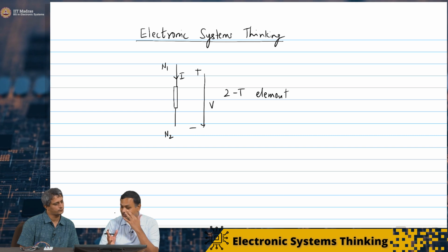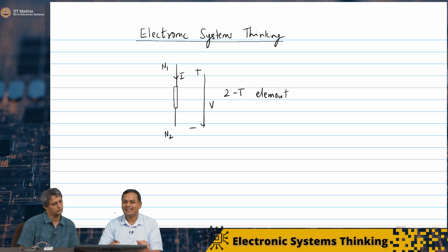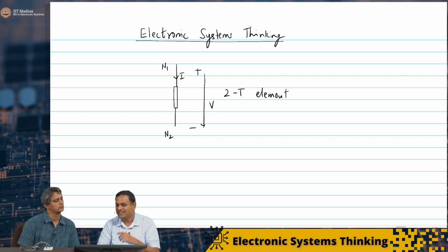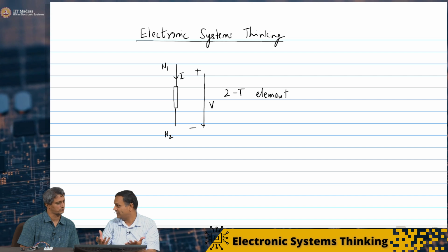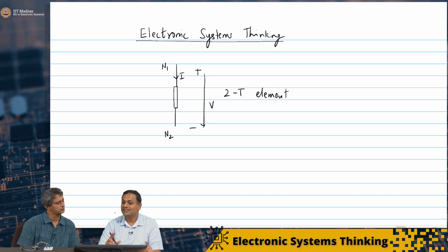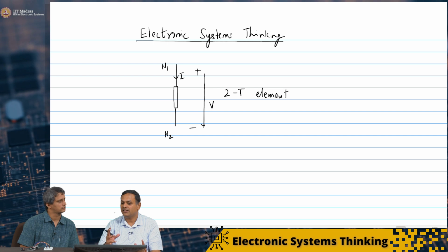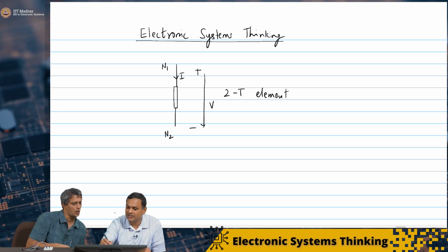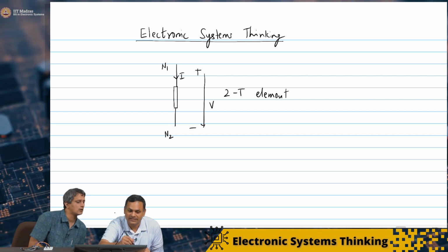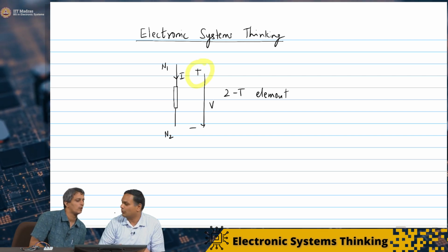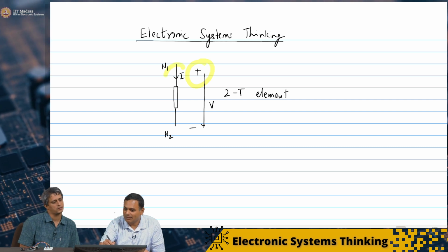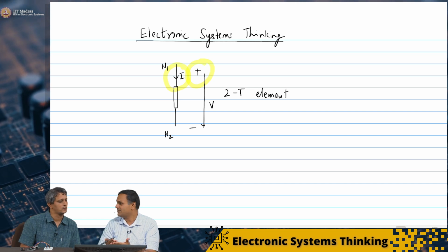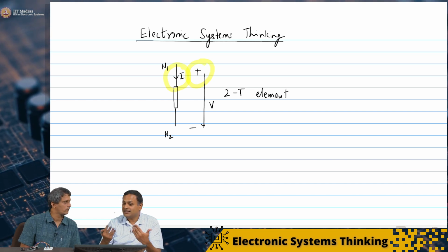So in electrical engineering, the general convention is that if the current is entering the terminal with the positive sign convention, then you think of the element absorbing power. So maybe I'll highlight it. That may make things easier. So imagine this is the positive terminal, and a positive current I is entering that positive terminal. Then if V is positive and I is positive, the power is V times I.